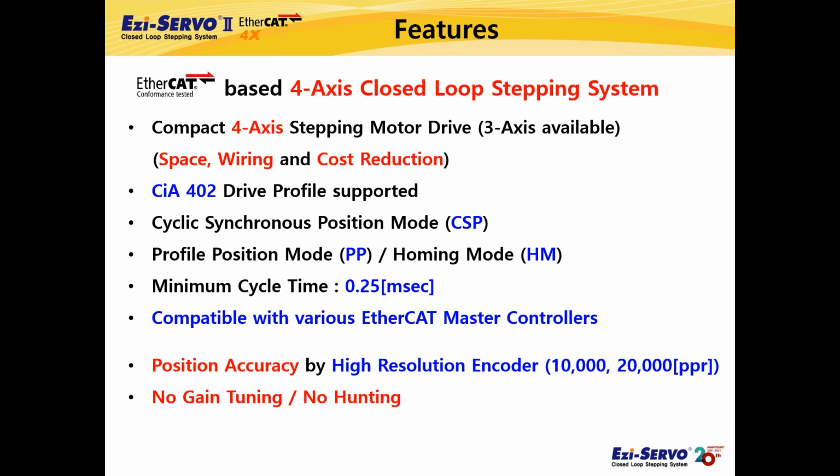Since the holding torque is large, there is no vibration after stopping compared to the servo. In general, when controlling a stepping motor, motor heat is a problem because the maximum current flows regardless of the load. But since Ezi-SERVO controls the current according to the load like a servo, it can relatively suppress heat generation compared to the conventional stepping motors.